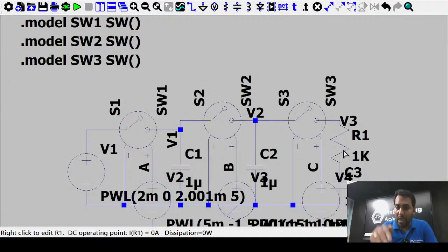You must know how C2 is discharging and C3 is charging, and that now it is not going to 2.5. C2 is not going to 0, C3 is not going to 2.5. It will have some limit. And you can change the question in this way: the capacitor values are changed. Here it is 1 micro, 1 micro, 1 micro; you can change it to 2 micro, 1 micro, 3 micro, it's up to you. Use charge conservation, simulate it and find it. What will be the output?